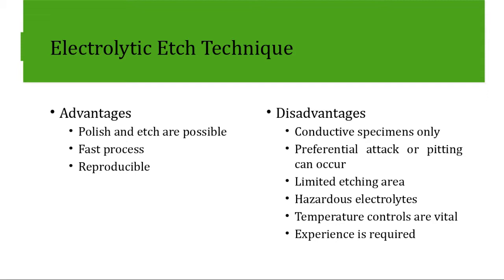And once again, if you're trying to identify true microstructures and you see pitting in your sample, the first thing you're probably going to say is, I have porosity in my sample. So that also leads to why we look at our samples prior to any etching technique that we will perform.